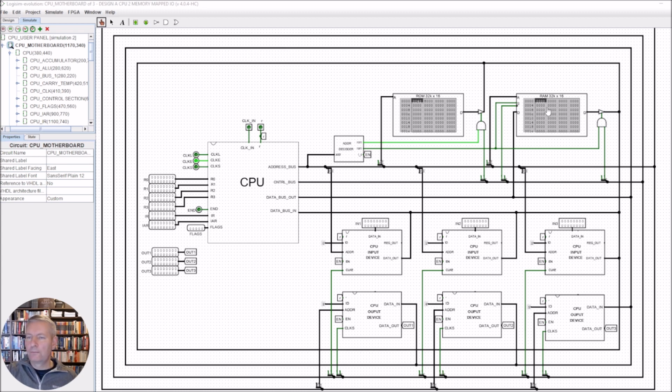But of course the RAM, we don't only just read from the RAM, we can also write to the RAM. So we've got to control the writing of information into the RAM, and we have to do that with the set. So it means that the control bus will come along here, and we're going to have our set. So our set's going to come off not pin 0 but pin 1. So it's going to get into the little clock set element here of the RAM, and the choice here of the set is going to come from the address decoder.